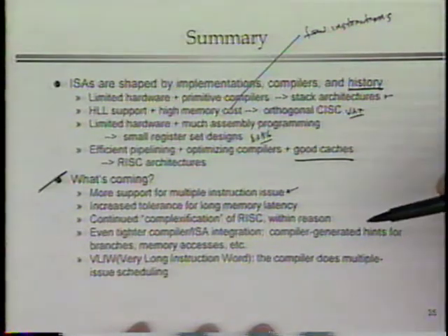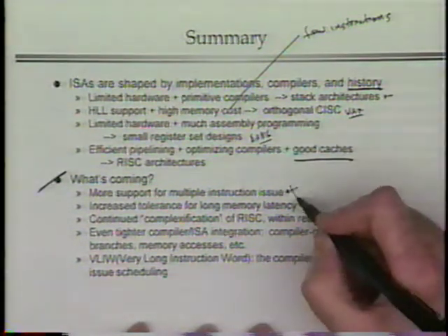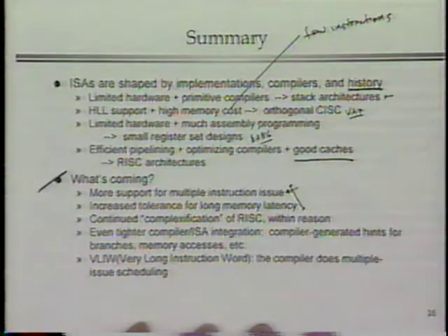other ways in the instruction set, like, for example, having more registers to allow more instructions to be executing in parallel. Sometimes, for example, more registers might be part of the architecture, things that the programmer actually gets to use, and sometimes they might actually be hidden real registers that are really not part of the instruction set architecture, but are there for the implementation to be able to more efficiently use the registers that the programmer specifies. And in fact, we'll see some of that later on.